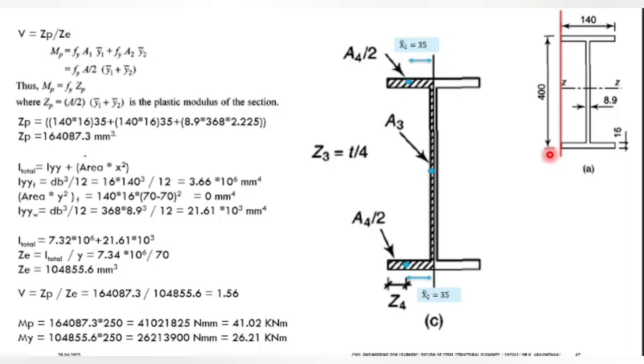Okay, what was the Mp at the x axis? Mp was around 290 kilonewton meter, which you took as the plastic resistance. Now when you are tilting this axis, how much is it taking? 41.02. Now can you find the difference? Instead of placing the beam 2 feet by 1 feet, if they would have placed it in another manner, the beam is going to deflect more and it is going to fail easily when the load reaches the limit. So this is the understanding by that.